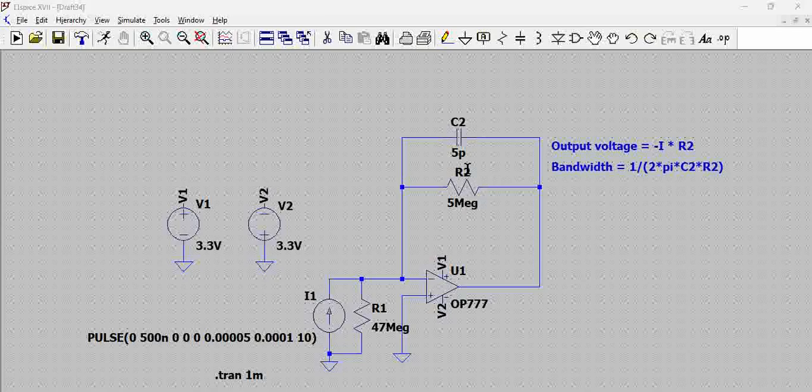And so we talked about the feedback capacitor, we talked about the resistor here, we talked about the type of sensor. The major point is the selection of this op amp. Okay, so the selection of this op amp is a very critical criterion here, because you have a negative output, which is the inverting terminal. If you want to see a swing on the output to the negative side, so that you actually know that this is the actual value it is reaching, you need to have an op amp with a dual supply.